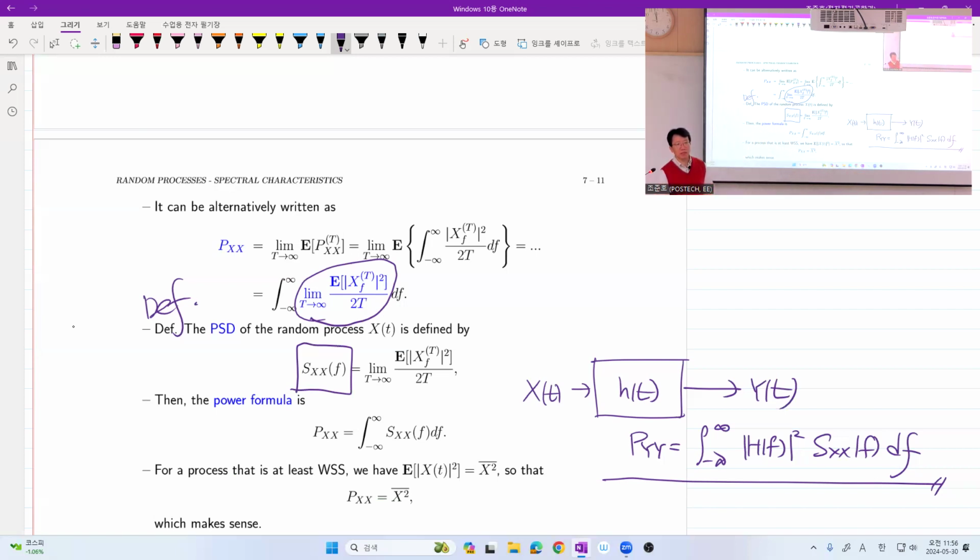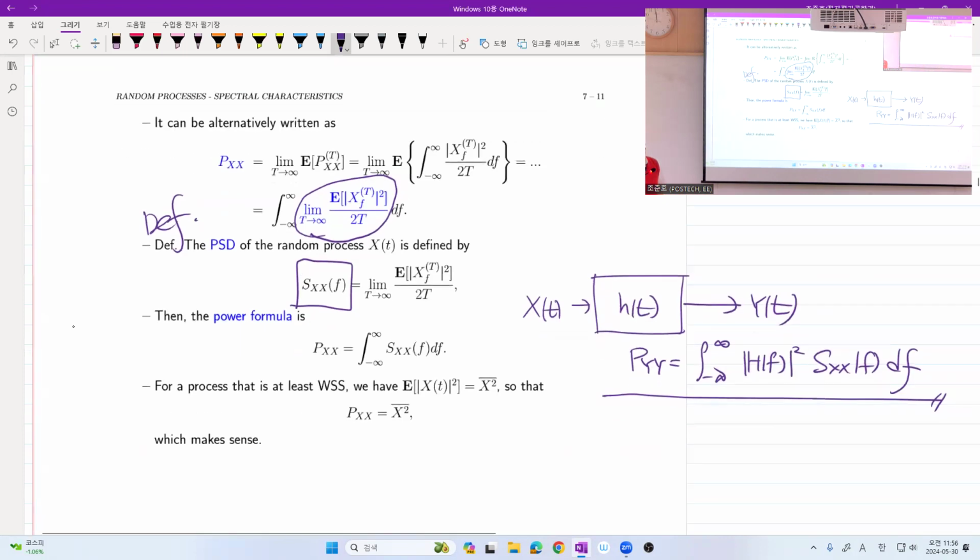That is very, very misleading because, for example, the spectrum analyzer that you, as an RF engineer or communication engineer, will use is actually based on the definition, not the Wiener-Khinchin theorem. What they do is take samples, truncate them, put some window, and do just a Fourier transform, a fast Fourier transform. And then they take the absolute value and do some kind of time average. Got it? So without realizing this is the definition of the power spectrum, you may have some problem.